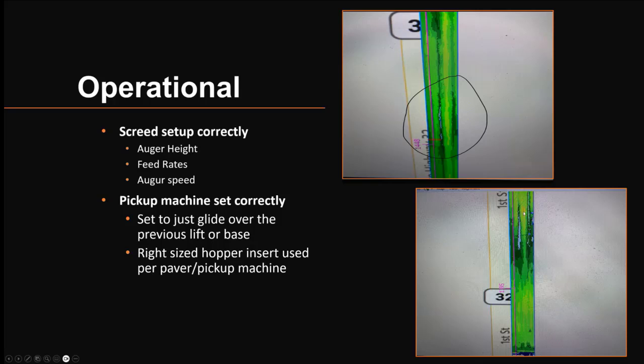But here you can see that same issue, but also this is probably a truck transfer of some sort, because right here you can see there was a paver stop. He obviously had a nice consistent pool in the hopper as he got through that. Then he started running into some issues.